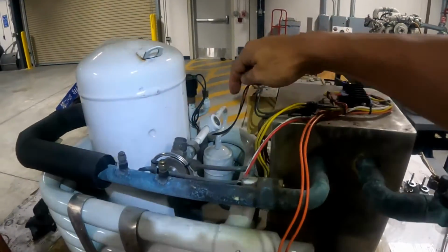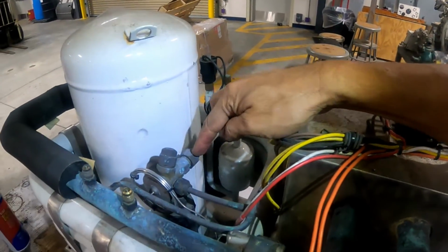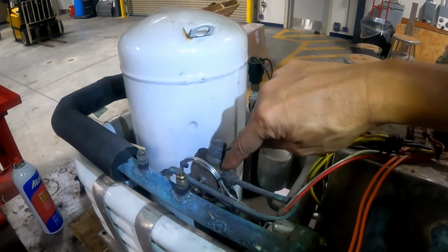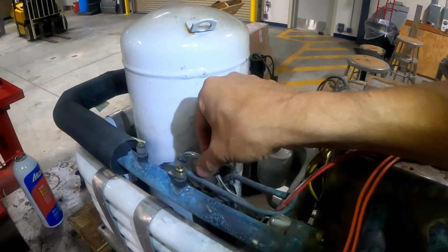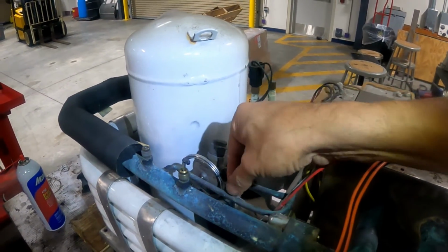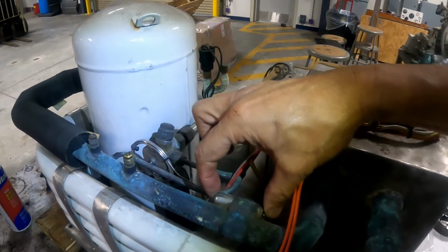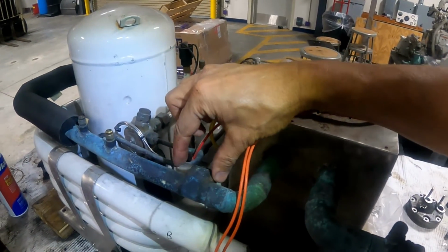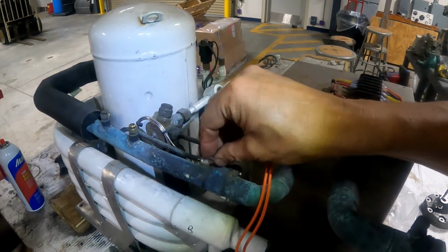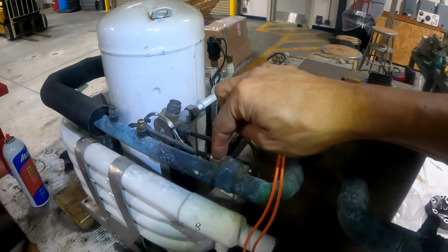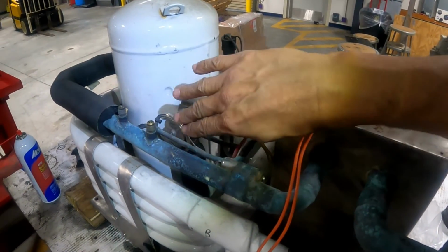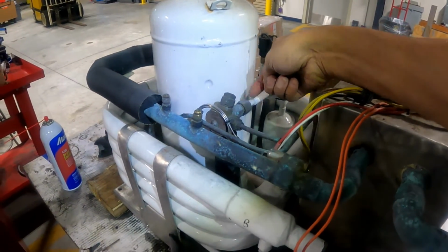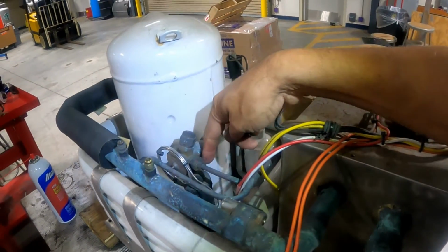Once again, this is the refrigerant with high pressure and high temperature, and this is the thermal expansion valve. The thermal expansion valve operates with the diaphragm internally opening and closing depending on the signal. The signal is coming from this small capillary pipe connected to this bulb. Internally in this bulb, they have a substance similar to mercury. According to the temperature of this, the mercury expands or retracts. Depending on how much it expands or retracts, the diaphragm moves back or forward and opens and closes, and allows the refrigerant to pass through the venturi.